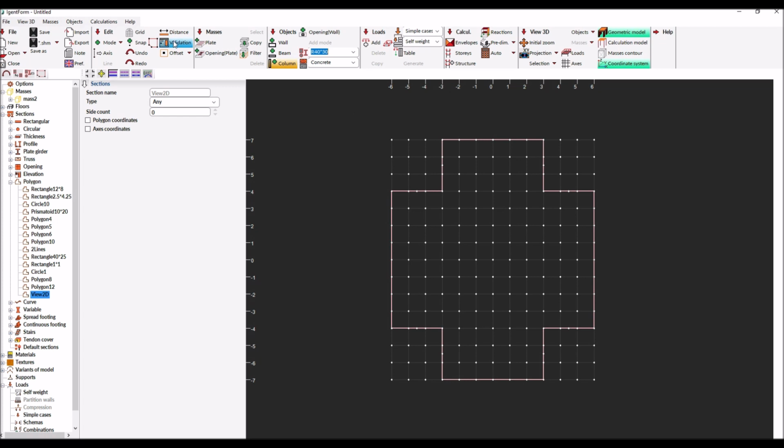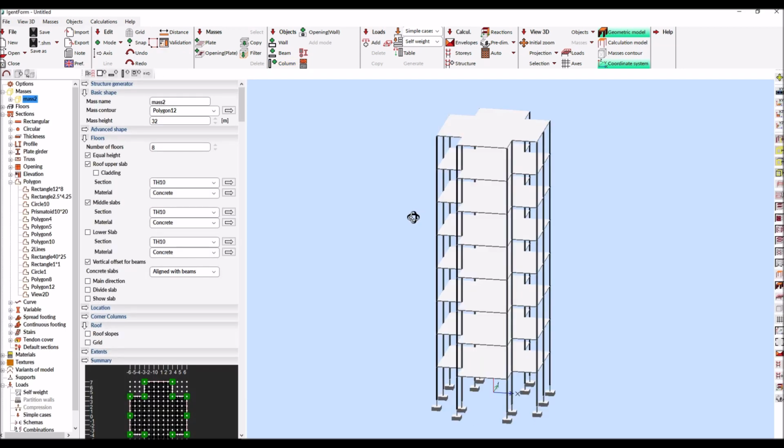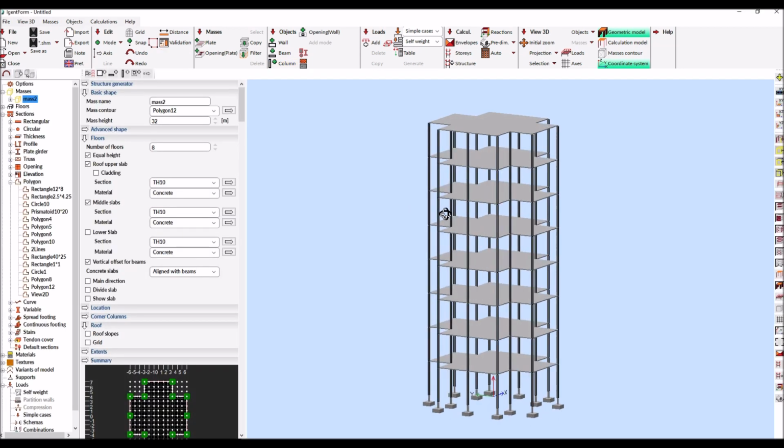We will now define the columns. First, we can change the default cross-section and introduce further elements in the desired places. After defining each element, it is possible to display a dialog for validation and possible modification of the entered data, for example, cross-section, material or offset. In this example, the default settings are accepted.